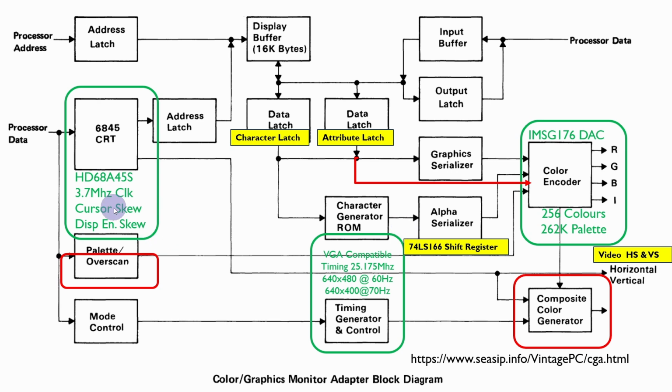And in fact, one of the reasons why we've got some delays here, and we also have to delay the horizontal sync and vertical sync signals, is because there is a pipeline here. So it does take a couple of clock cycles for data to get here and to arrive out here. And if we don't include some delays in some of these other signals, then what in fact happens is we miss one or two characters. And we'll see that during the videos, that when we don't have these things right, then we may miss half or a full character in some cases.